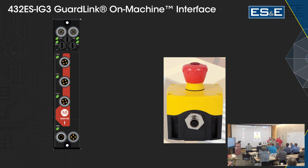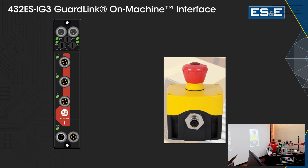So this is a tap, and for each device I have to have a tap, right? That's correct. And you've got 3 channels on here? Yep, there are 3 trunk lines. How many taps can I hang off each trunk line? Each trunk line can support up to 32 taps and devices. So I could put a total of 96 devices per module. If this machine got a whole lot bigger and I had e-stops throughout the line, I wouldn't need to run any wires to know which e-stop was pushed, because it would tell me? That's correct.